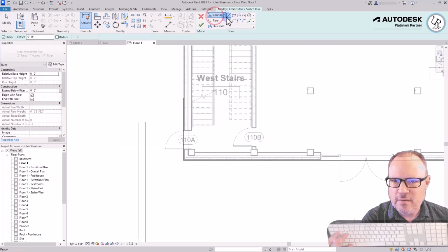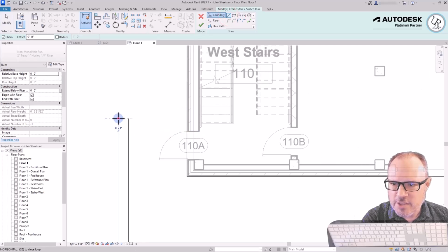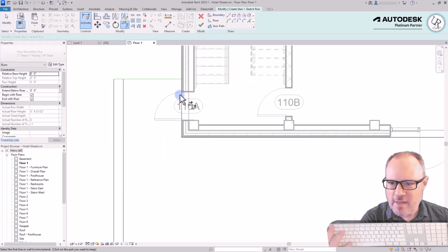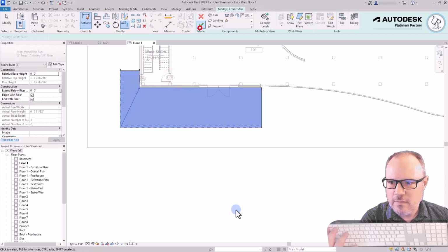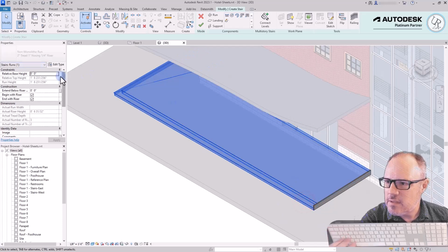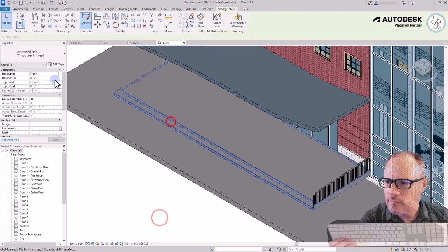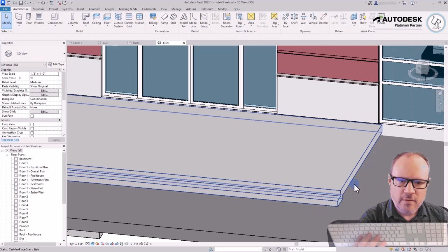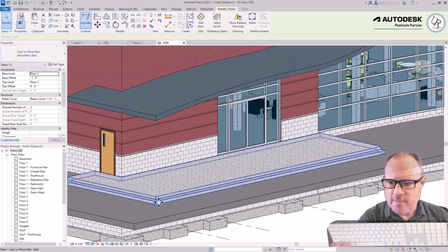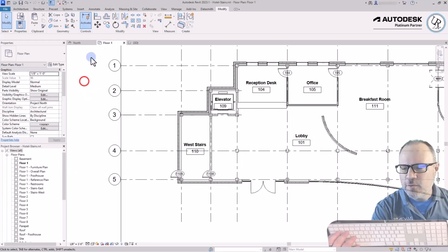and then I create a boundary line that goes from the edge of this stair back to the wall, and make sure everything is trimmed together without any extra overlapping lines. Once that finishes, look at this in a 3D view, set the elevation height of this correct, coming up that full height, and creating a custom stair design, meeting up to that landing and reaching the door 1 foot higher.